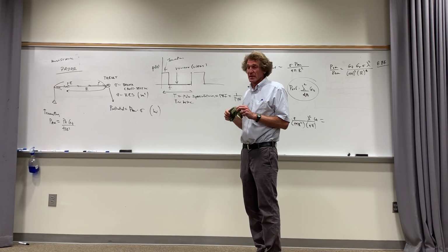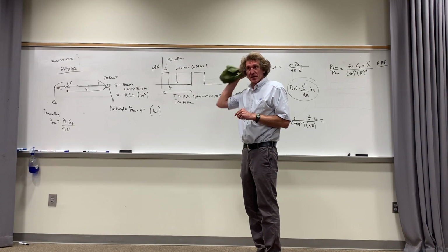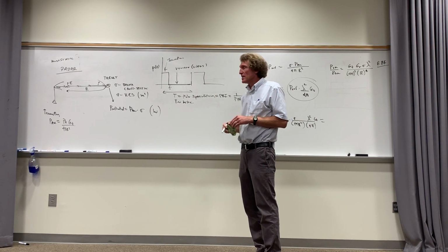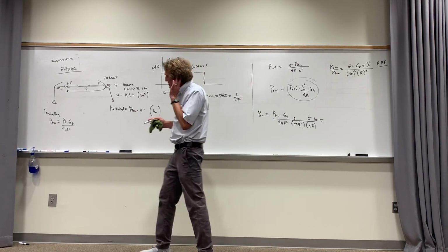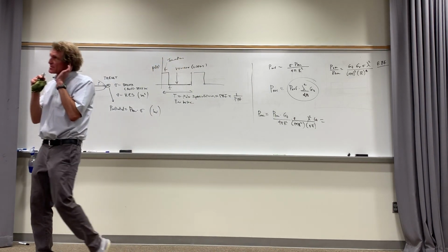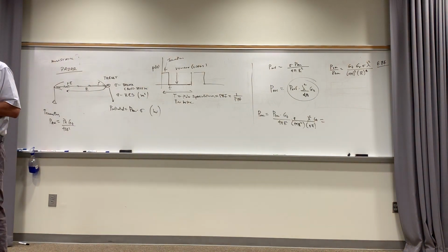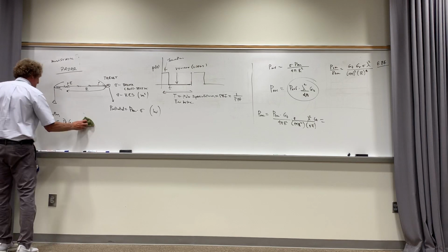And that's important to understand. Because the way that they actually gauge whether there is or isn't a target out there is as they listen, when all of a sudden the power density that's being recovered at that frequency goes above a certain threshold, they say there's a target. And they can get the range by the timing delay. Right? So that's sort of a primitive way to think about radar. Next.